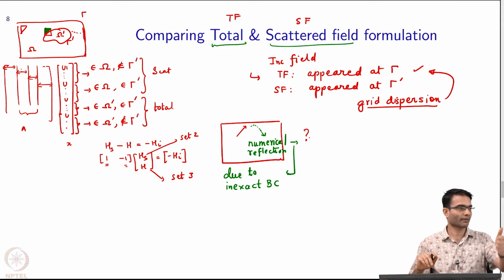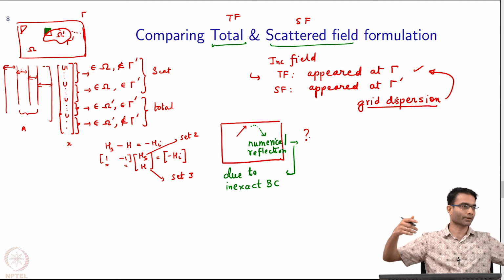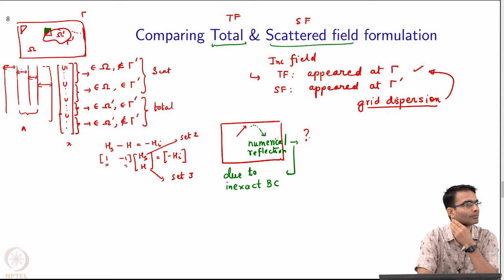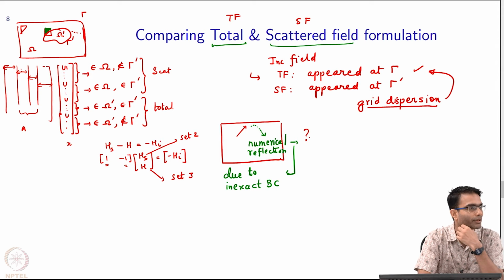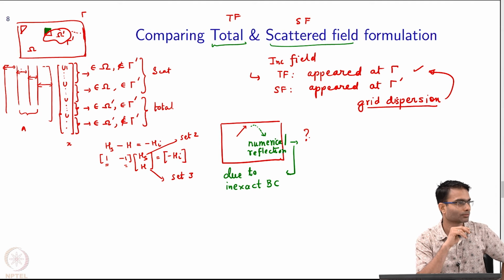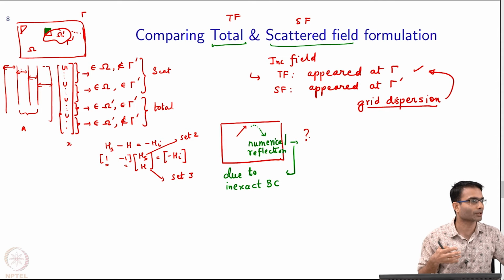Real life situation, you have an antenna here, and it's sending out some fields, you don't want the fields to come back to you, basically. That's a reflection. I want to cut it out. What would you do? Supposing I can't increase the boundary. I mean, I'm in a room, I can't make my room bigger. Put some absorber. If I put an absorber, then nothing will come back to me.